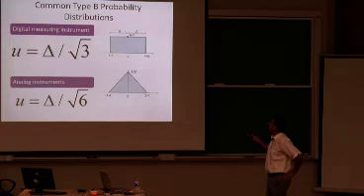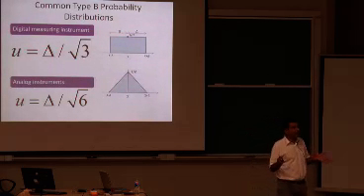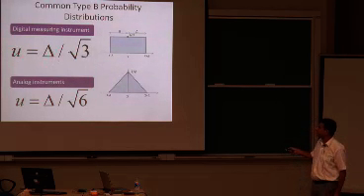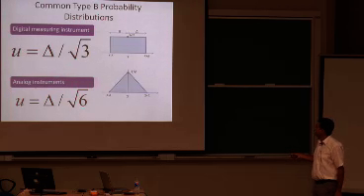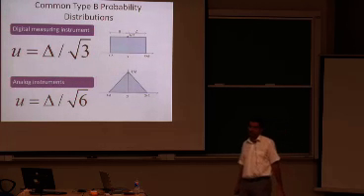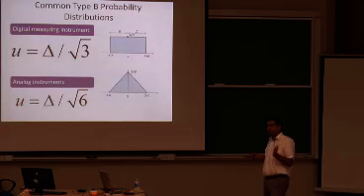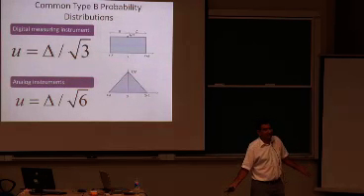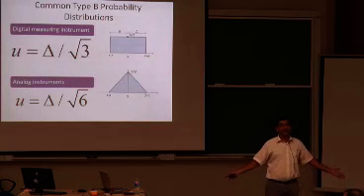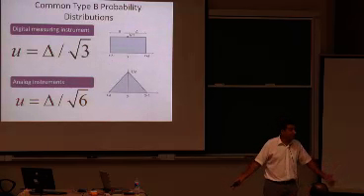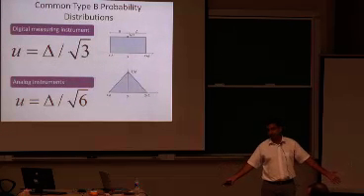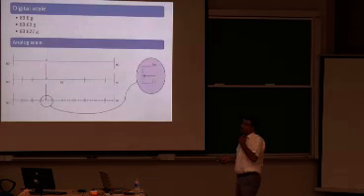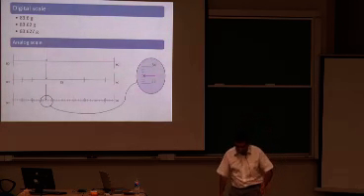Now, if I have a digital measuring instrument, associated with the scale is a uniform probability distribution function, and the uncertainty u is given by delta over under root 3. Now, if I have an analog instrument, generally the probability distribution function associated with it is triangular, and the uncertainty is smaller. It's delta over under root 6. It's smaller, and there's a particular reason for that. Now suppose you have a digital scale, for example, this balance scale.